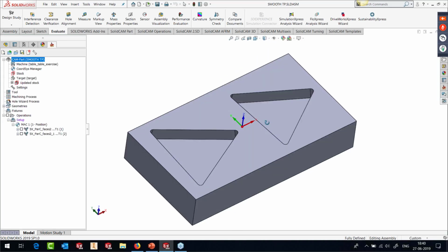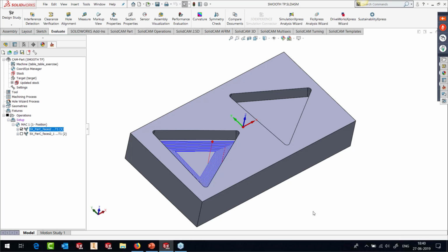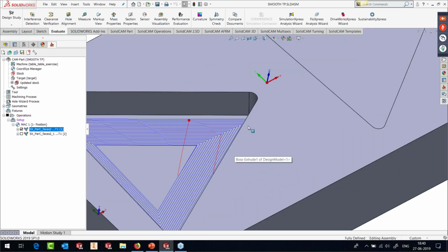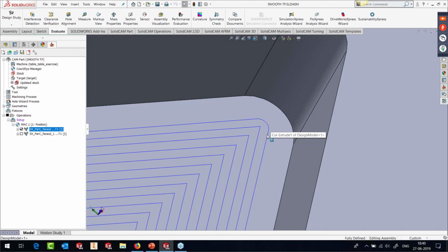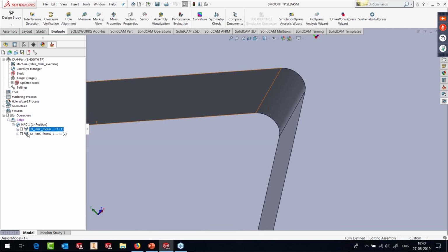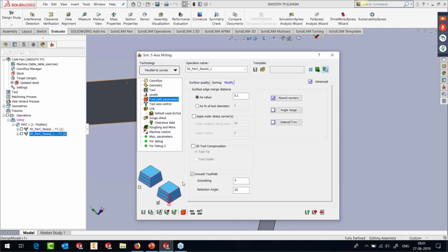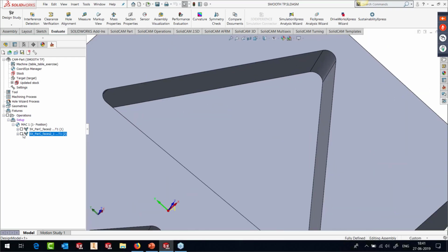Okay, so here we have a toolpath which does not have the smoothing but only has a corner rounding. In corner rounding, you can see that only the last pass is rounded, whereas the other passes still have a sharp motion. By switching on the corner rounding option or the smooth option in toolpath parameters under modify, we switch on the tool smoothing option. When this is switched on, my result is completely different.